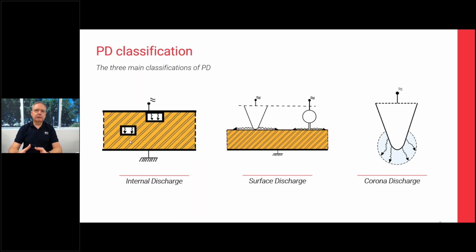During a maintenance period, if you were to open something up, you could potentially see surface discharge. If you open something up and something is happening deep inside the insulation, you'll have no visual indication of that, and therefore you won't target activity towards that. So it's possibly the most dangerous type of defect that you can come across, because you don't get that prior warning based on visual or other sensory indications.